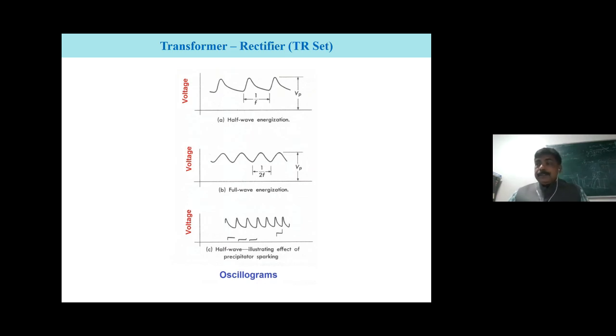Usually when someone says direct current, the immediate imagination is one horizontal straight line parallel to the x-axis, and that is what DC is. But it need not necessarily be. DC means the current which doesn't change its direction. So the voltage or current curve over time will not touch the x-axis. Here all these three currents are direct currents. The only thing is the voltage level varies.